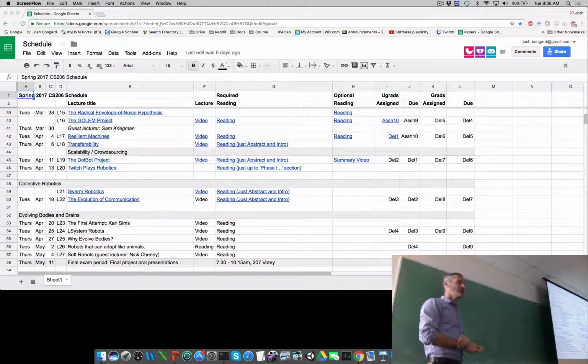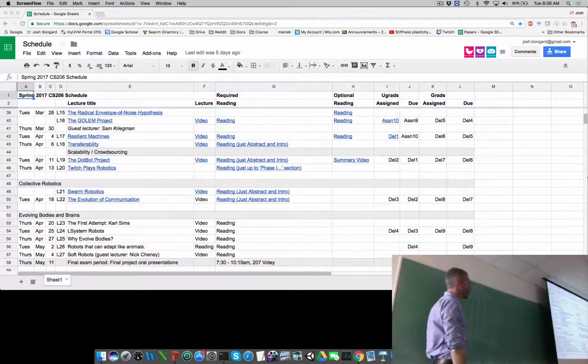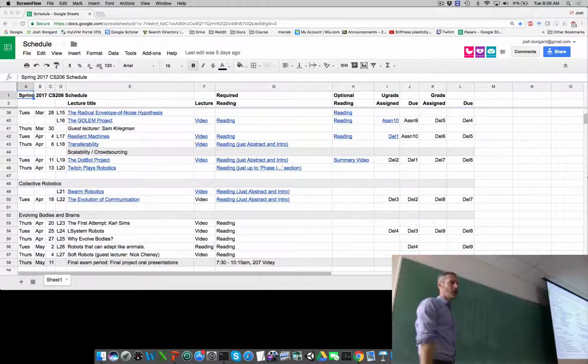It's not an easy thing to build up intuition for how to build good fitness functions. One way to think about this is, again, your fitness function is always going to be a function of sensor data, right? You can get whatever sensor data you want back from the simulation. What do you do with that sensor data? Let's imagine, for example, that I'm still working with the quadruped, and it has its 4 touch sensors, T1, T2, T3, and T4. And let's imagine, just for the sake of convenience, I'm going to get back all of the sensor data and I'm going to place it in one big matrix where every column in this matrix corresponds to one of the